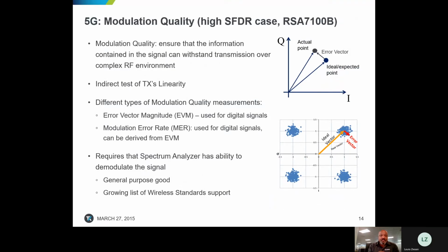Now, these characteristic eye patterns that you see here over in the bottom right are related to decision points on the I and Q axes. These are orthogonal signaling pairs, which form the basis set for communication of this data. So clearly, there are 4 decision regions here, and the user can disperse the data across these 4 decision regions. And because of the strong dynamic range, in this case of the measurement equipment, analysis of the transmitter and its performance can be done effectively.